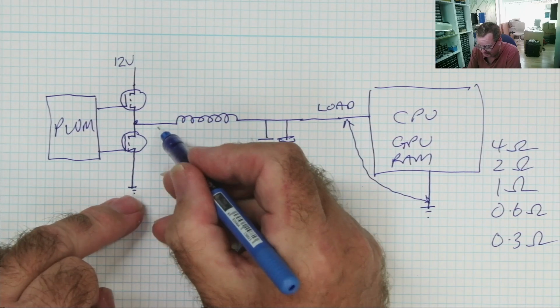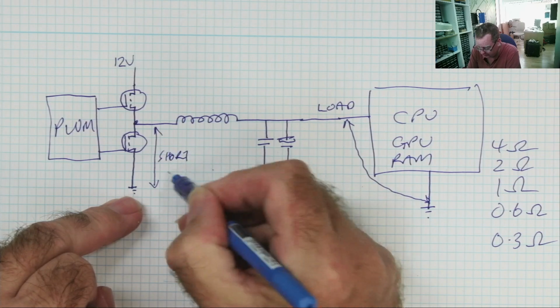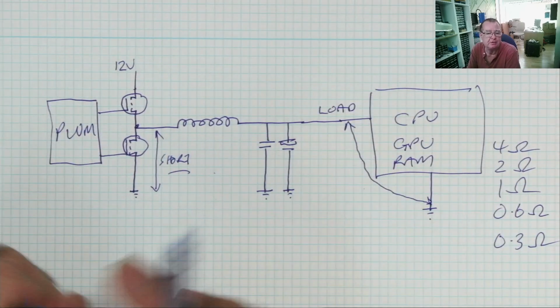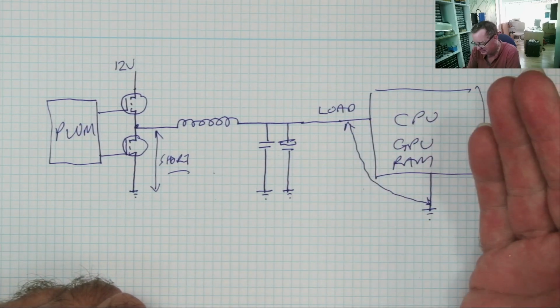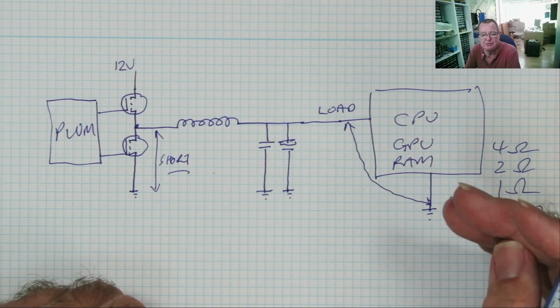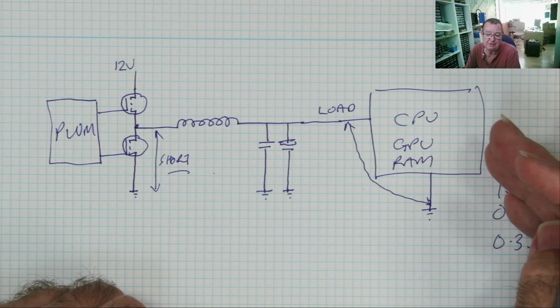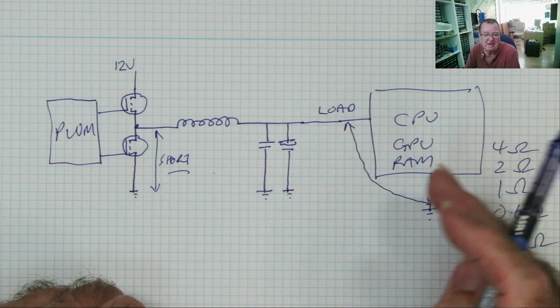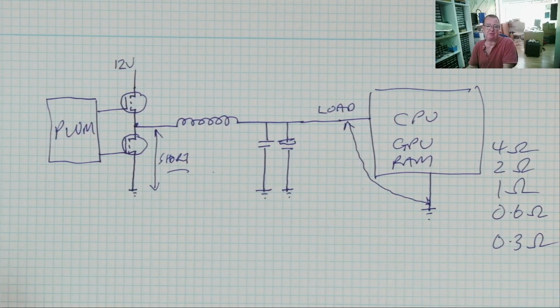This will read often like a short. And you think you've got a short circuit on this voltage rail. You haven't. You've just got a very low resistance load. But unless you use resistance mode, and on some later GPUs even a micro ohm meter, you cannot see that it looks like a short in diode mode. Let me show you a few examples.